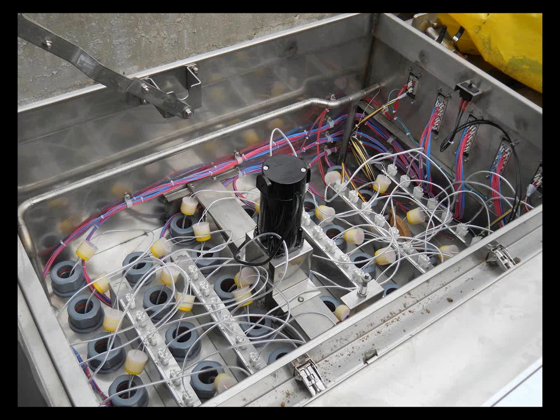The little black motor you see in the center of the box, that's the wiper motor. Each one of those quartz sleeves has a plate around it with a rubber wiper, and that wiper goes all the way down to the bottom and comes back up. It is set at periodical intervals, and everybody's will be different. I think we do ours once an hour. Maybe if your wastewater had a little more stuff in it that would cause it to build up on the bulbs, or the algae was worse, you'd have to do more. But we do ours about once an hour, and we try to have it run while there's flow because it actually helps rinse stuff on by. But sometimes it doesn't work out that way.